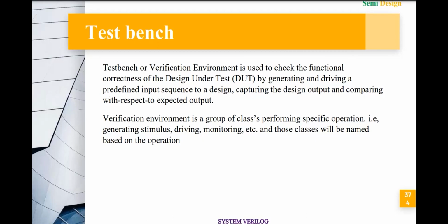Okay guys, this is the SystemVerilog session we are going to discuss. We have completed all the topics of SystemVerilog, from the data types and different types of arrays, to how to create a mailbox, OOPs concepts, coverage concepts, randomization, and constraints concepts. By using all those things, how can we create the testbench using SystemVerilog?